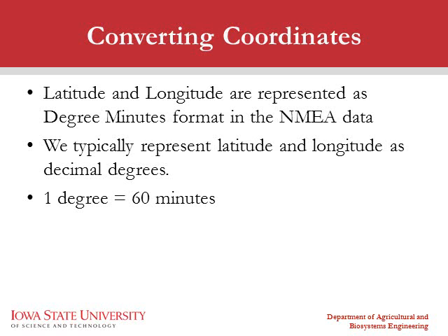So let's talk through converting these latitude and longitude coordinates. In the NMEA data, latitude and longitude are represented in degrees-minutes format. We typically want our information in terms of decimal degrees for latitude and longitude. It's a simple conversion between the two, knowing that 1 degree is equal to 60 minutes of latitude or longitude.